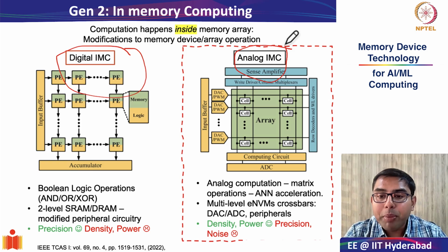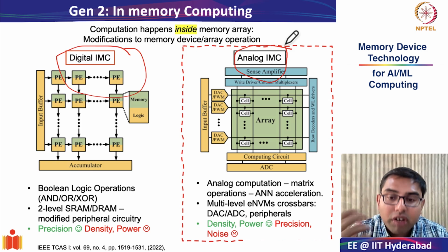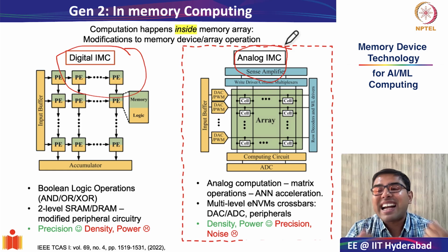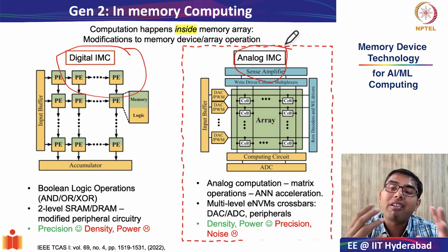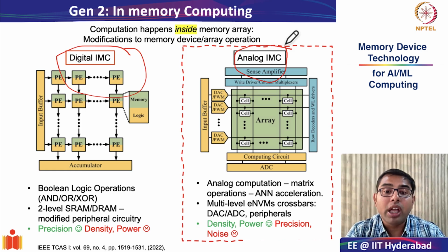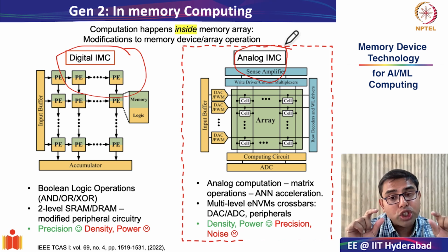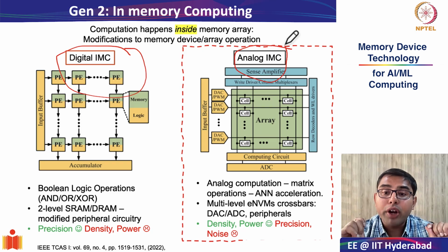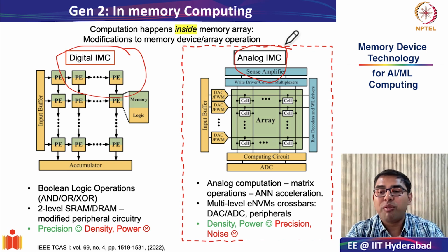Using concrete examples, we saw in the case of digital in-memory computing, how activation of simultaneous word lines, both in DRAM and SRAM, enables all these Boolean logic operations directly inside the memory. We also looked at a specialized case, remember, of doing partially analog vector matrix multiplication with digitally stored weights using the SRAM based structures. And this is what will slowly enable your mixed signal MAC operations.